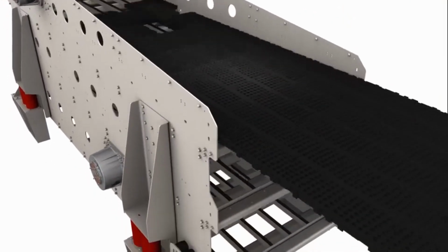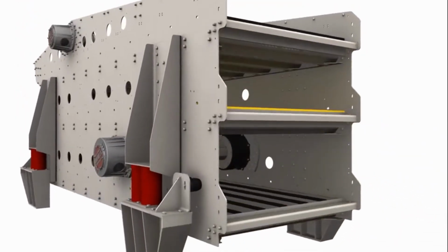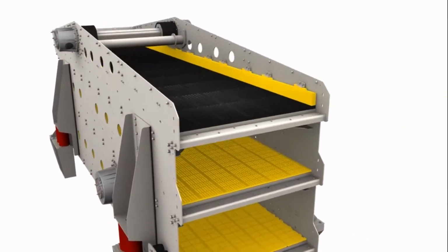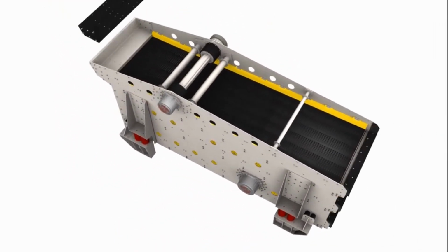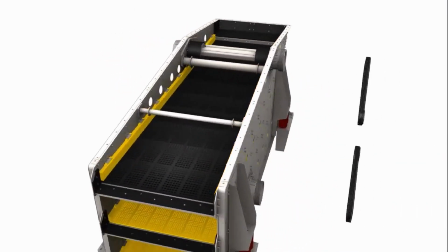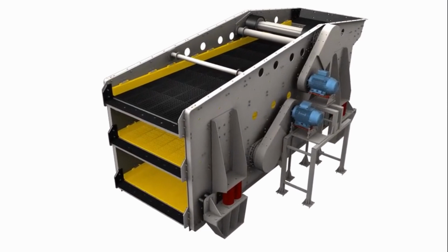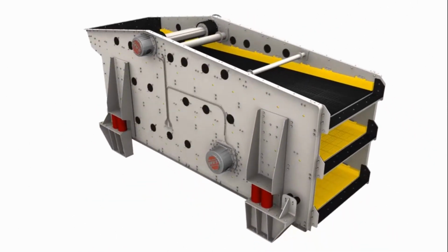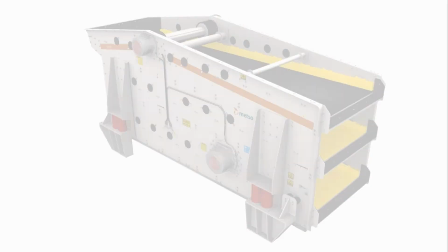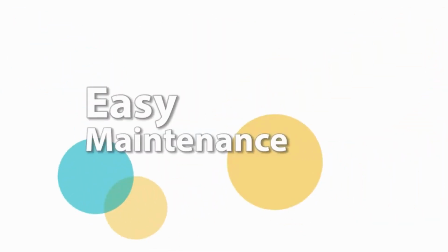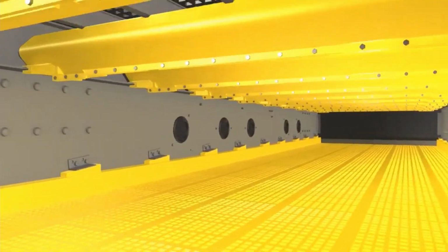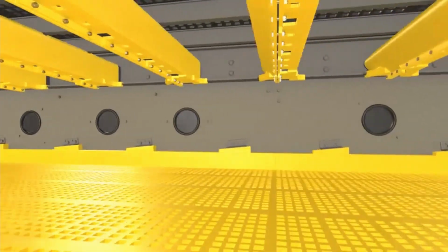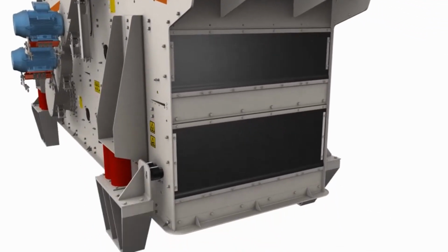Well, by doing this, by changing the stroke and configuration of your screening, you can reach higher angles. Okay, if you increase the angle, what's going to happen is you reduce the time that your material is going to be held inside of the equipment, and then you have more throughput, you produce more material. Okay, the video is going to continue on, but it's going to show you some mechanical parts of the equipment. And to tell you the truth, we're not so eager to see lubrication circuits and things like that, but you can see all of this on YouTube later on.